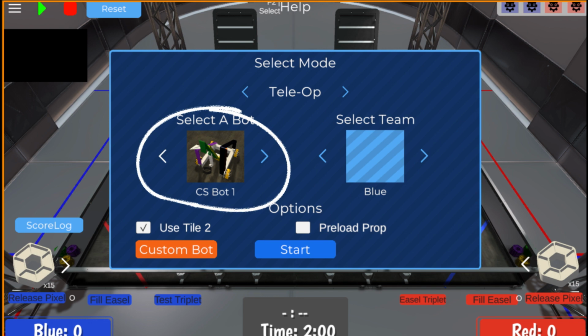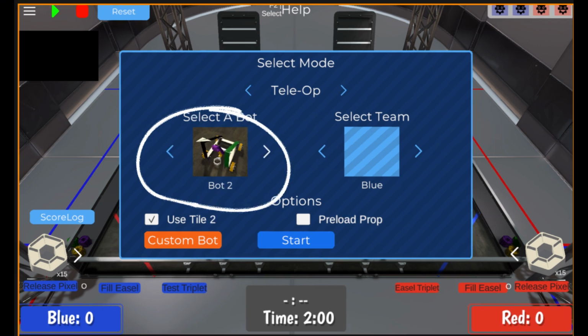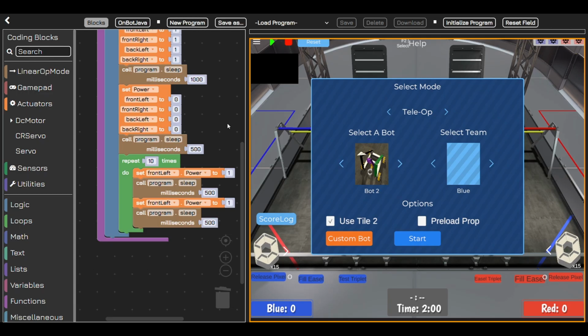Keeping these variances in mind, such as the fact that Bot 1's arm shifts but its pixel holder stays fixed versus Bot 2's static arm but adjustable pixel holder, will help inform programming strategies and account for potentially different results when operating Motor 6 on the 2 distinct bot configurations. We keep the same code as before, trying to make the robot move forward, and then move Motor 6 up and down to visualize the motor's movement.